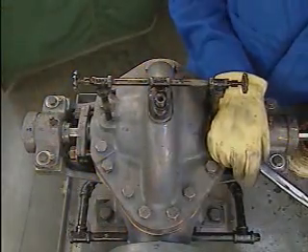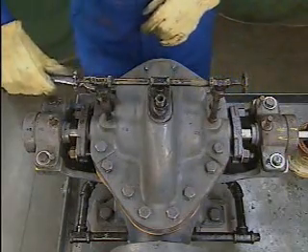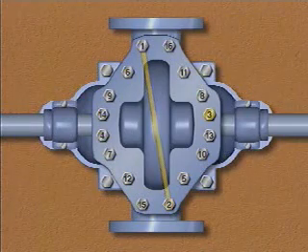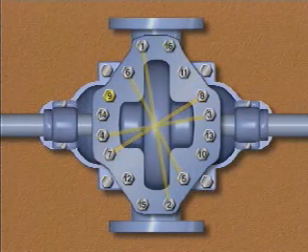The pump's manufacturer recommends that the bolts be tightened in a specific sequence to prevent damage to the sealing surfaces. This is the tightening sequence for this pump. Like other tightening sequences, it is a crossing pattern.